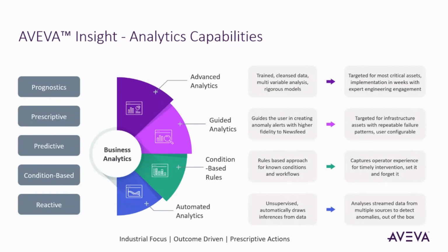Using supervised machine learning, the system can learn what the normal operation conditions are, for example, high loading, low loading, ambient conditions. And we can start to develop models based on those different conditions. Guided analytics is particularly effective for process anomaly detection in hybrid industries. It can be used for most generic assets, and it's, again, easy to set up with another built-in wizard interface that walks the user through the configuration of detection of this data.